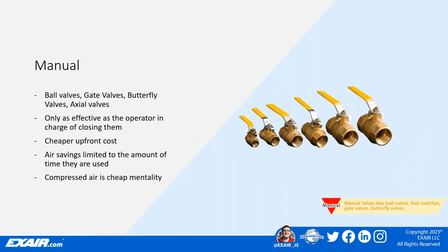So ball valves, manual valves, gate valves, butterfly valves, axial valves, they're great for applications where compressed air is needed for a long duration, and you're not shutting that compressed air off frequently, such as the end of a shift, but you are still relying on an operator to turn that valve when the compressed air application is no longer needed. While this is typically the cheapest and easiest way to add some control to your compressed air system for any given application, your cost savings is limited to the if question. If the operator turns that valve, you'll get the value out of that product.